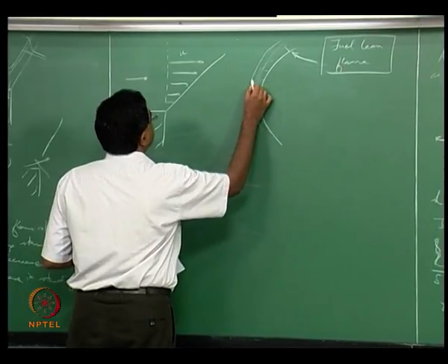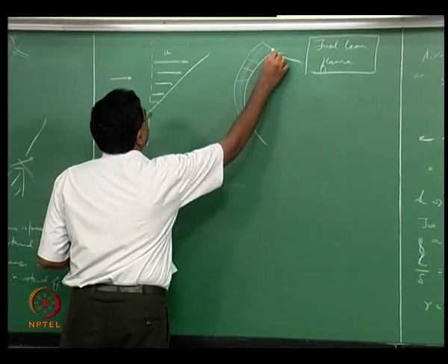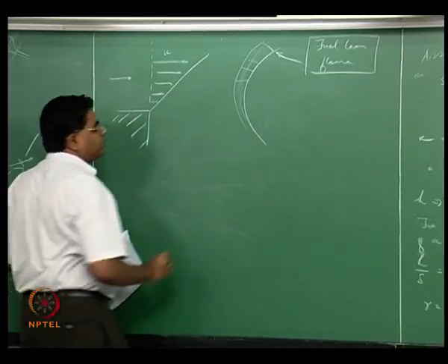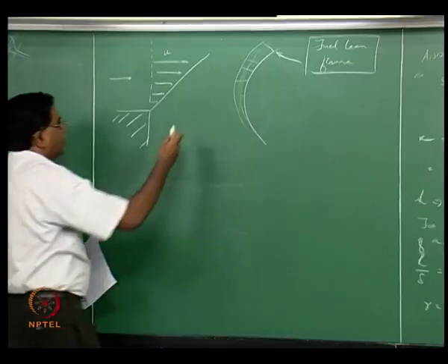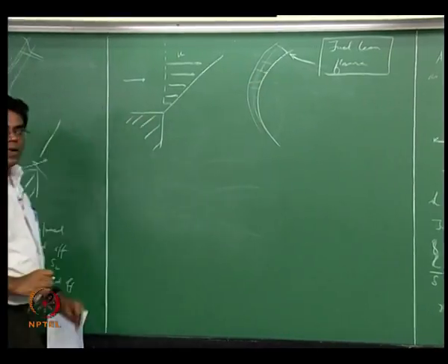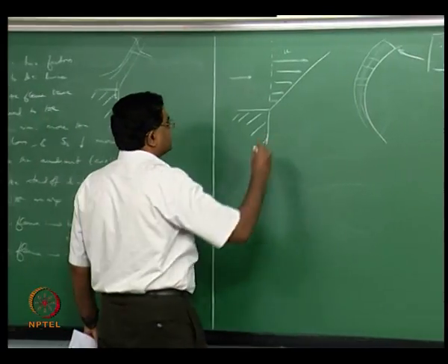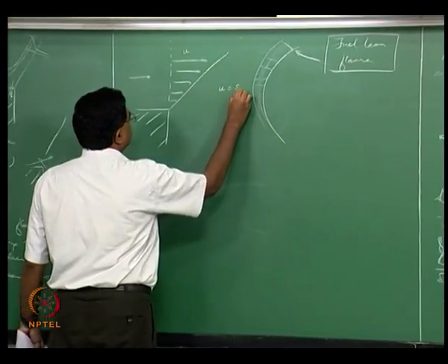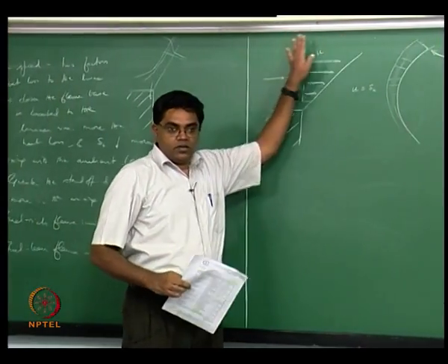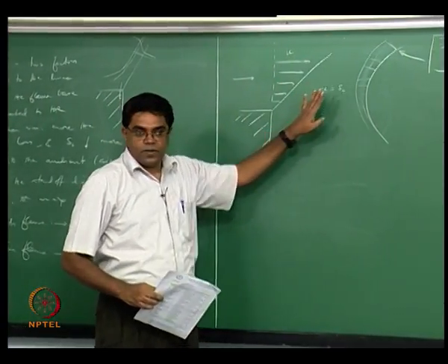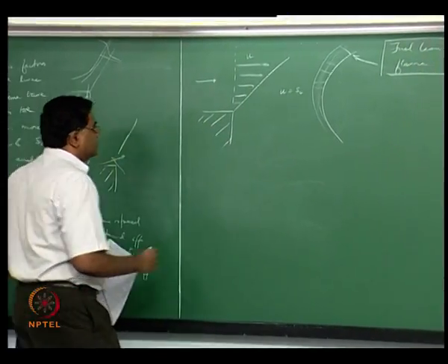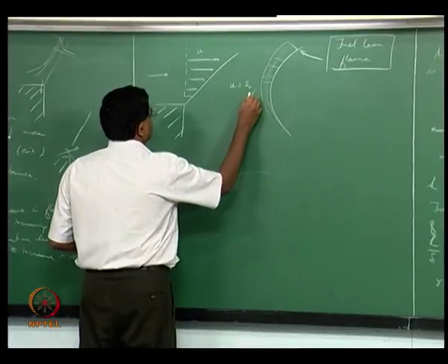So there is a condition when the local velocity and the local flame speed match exactly, where you have this curvature facing the flow, right. So this is where you now have U equals SL. I am not saying U bar equals SL naught or U naught equals SL naught, okay. I am saying U is equal to SL. So this is the stabilization condition.